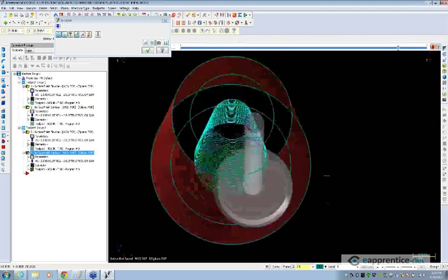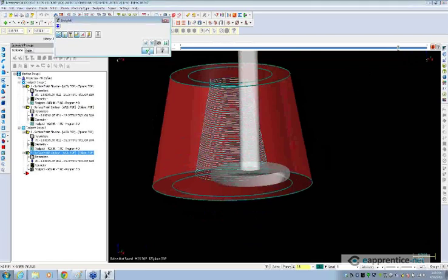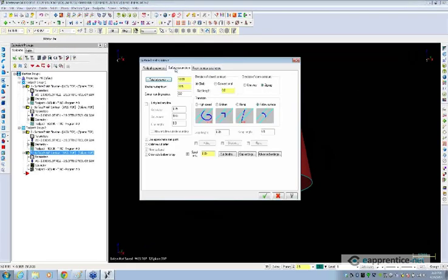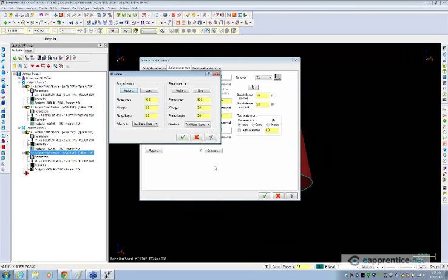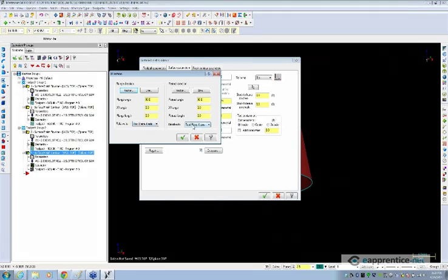So what's the last thing that we need to do now that we're getting some nice clean motion? That's right, we need to adjust the direction. So we'll come in here and enable direction. In this example, I'll just use tool plane x-axis. Now, one of the advantages of tool plane x-axis is that it's going to treat the 0 to 360 degree start, stop point, and direction the same between the entry and exit. That's not true for cut direction. So cut direction is going to be based on which way the cut is going and where it's leaving off on the surface. So you have to be a little careful with that.